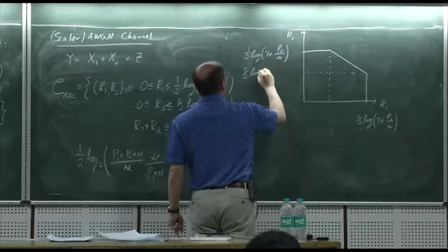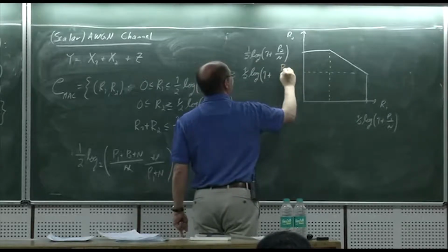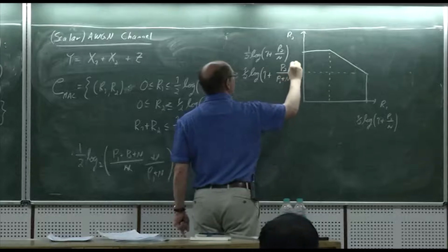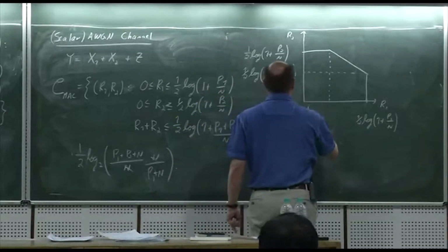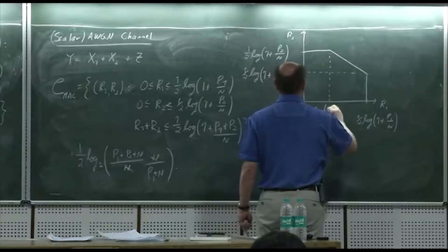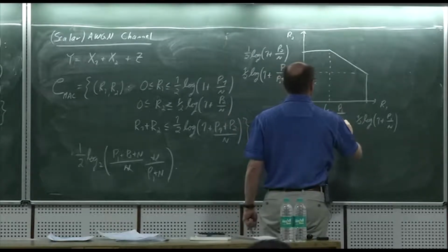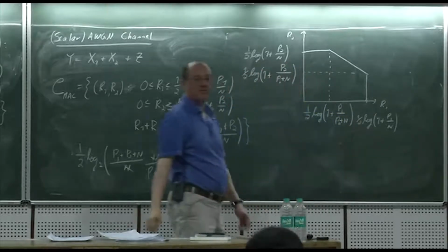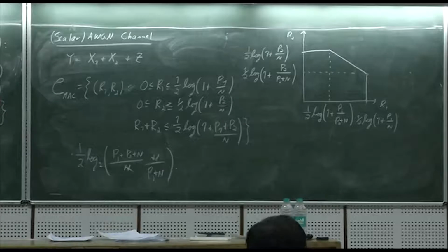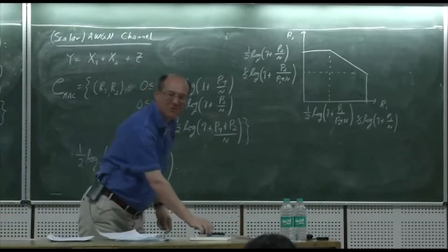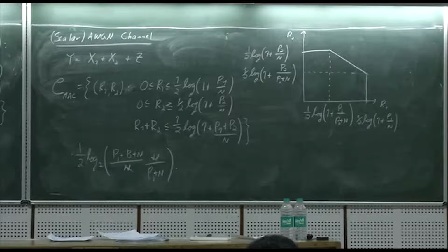1 plus the signal to interference plus noise ratio. So that's very nice. We're always working with signal to interference plus noise ratios, and that suggests, of course, something quite important. Namely, it suggests certain receiver architectures, which are very important in practice and weren't so obvious, and are all the rage now with NOMA again, non-orthogonal multiple access. You use successive interference cancellation, so we'll talk about that in just a second. Of course, these methods are as old as multiple access channel theory from the 70s, so there's nothing really new conceptually there. Again, tailored to the newer channel models, perhaps.